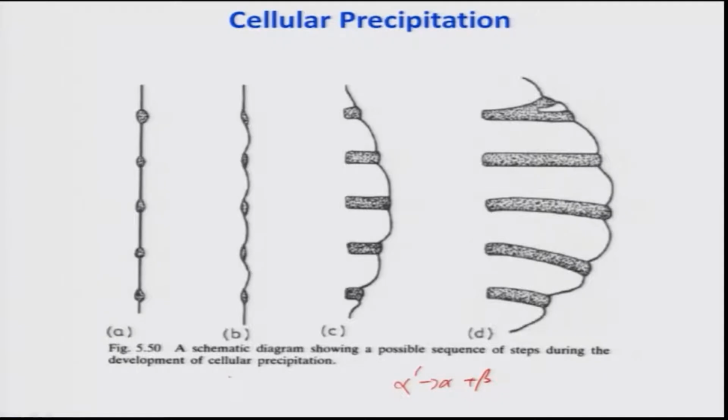As the precipitate grows, it takes the grain boundary along. So the grain boundary also moves, and that is why it is a different type of phase transformation as compared to the normal precipitation. But if you look at even these pictures carefully, normally these precipitates nucleate on the incoherent grain boundaries. Basically it is initiated by formation of the lamellar colonies at the incoherent grain boundaries.